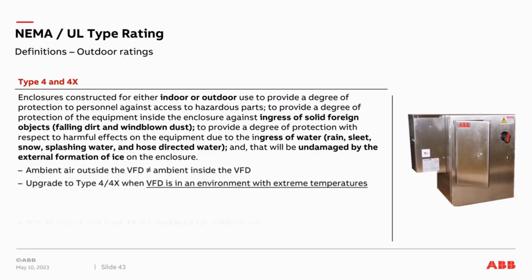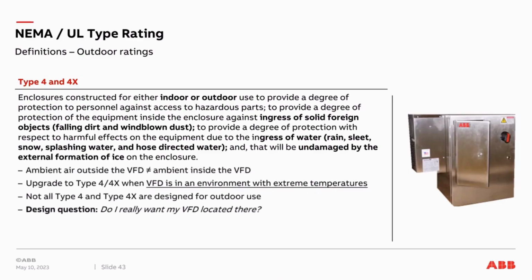The ambient air on the outside is not equal to the ambient air inside the enclosure. You can upgrade to Type 4 and 4X when the VFD environment has extreme temperatures. Not all Type 4 or Type 4X designs are for outdoor use. Sometimes they're only for indoor use. It depends if they're designed for sun loading. The real question you have to ask yourself is, do you want to put the VFD where the location requires a 4 or 4X enclosure?